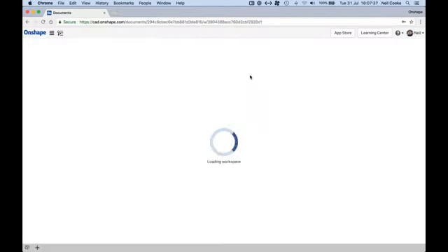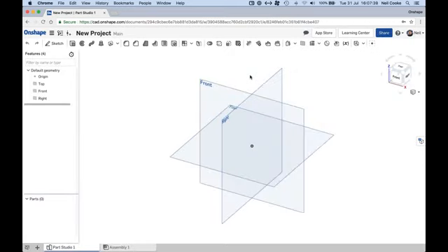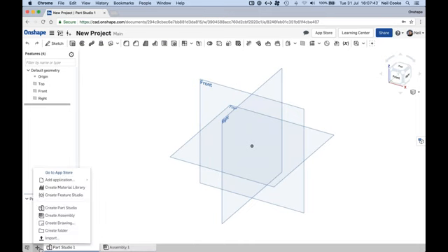Because, like I mentioned, when you first create it, we'll see that there is something called a part studio, and there's also an assembly. But this little button in the bottom left-hand corner will allow you to create more parts, more assemblies, drawings. You can create folders to organize it. Then there's other different things up here. Feature Studio is for a macro-like programming language, creating materials.